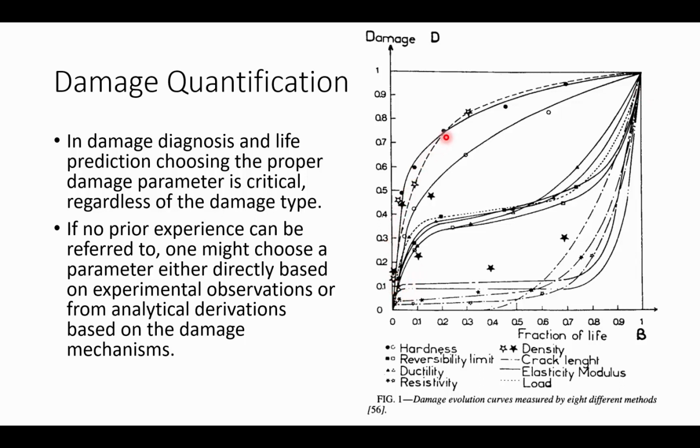Others are almost hardening behaviors, where they harden to the value of 1. So it demonstrates that if we can identify a good damage quantity, then when we take our samples, say from the F-16 fighter experiment, we can be measuring these damage quantities. We can be measuring hardness, or using some of the different quantities, the physical damage, and compare that to what we end up with as cycles to failure.